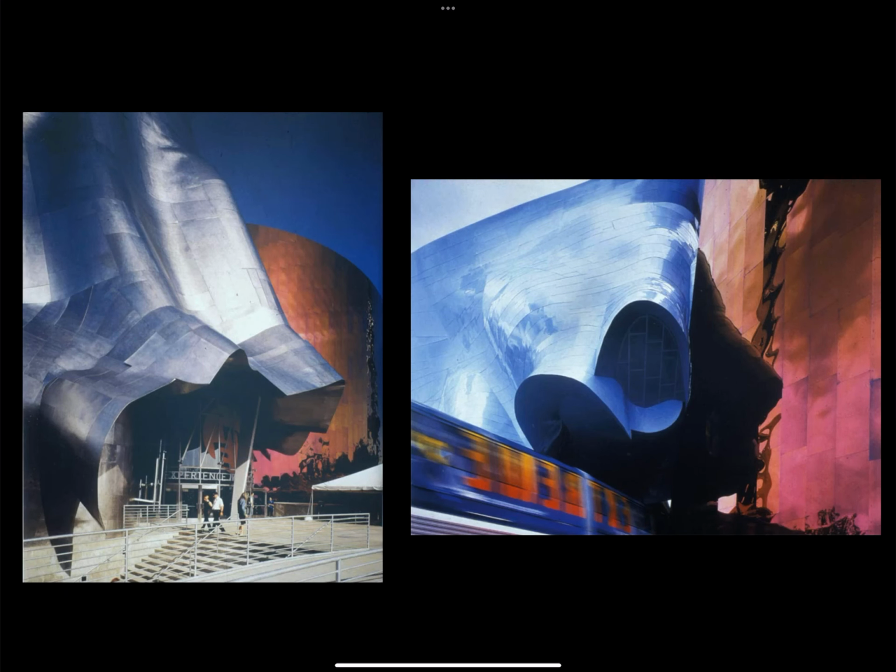The most common metals that are used for cladding are steel and aluminum. And if we were to compare them, there are many different attributes that we can compare. In terms of weight, steel is heavier and therefore may require more supporting structure. And aluminum, as we know, is super, super lightweight. So this is why aluminum is used to build airplanes and boats.